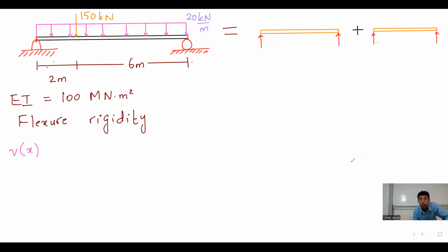So I'm sure that you have figured it out. This will be the strategy, right? I will put a concentrated load like this. And then I will put the pink arrows. Agreed? Where? Boom. I'm sure that our students already knew this. So now technically, what you are going to do is follow the example that we covered last time. Get the V(x) from there. And then you will add them together.